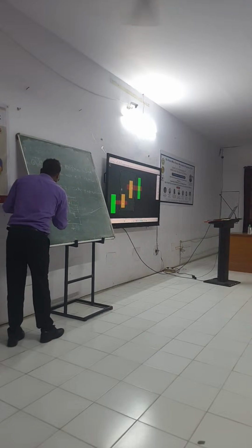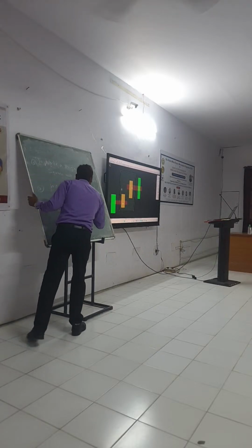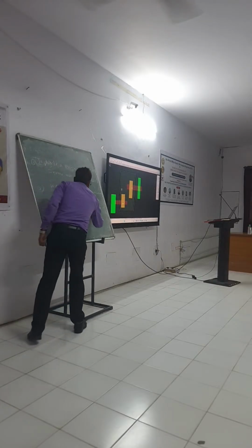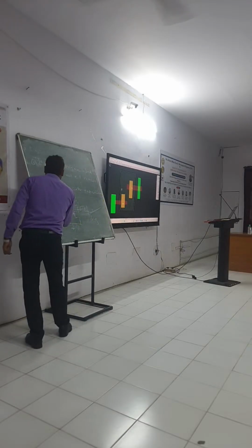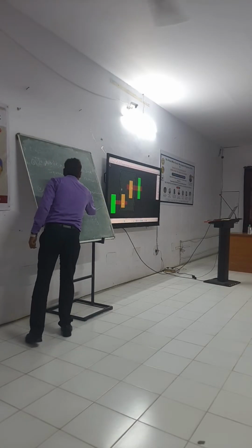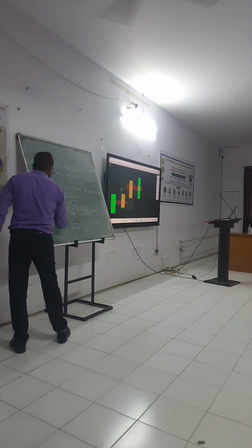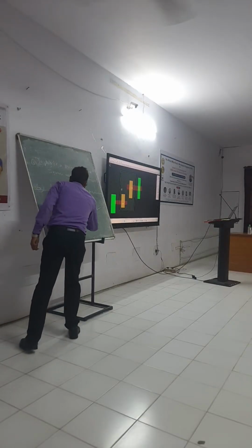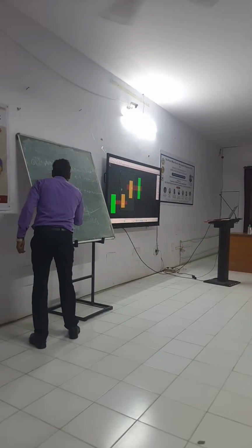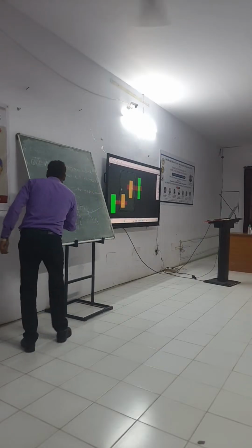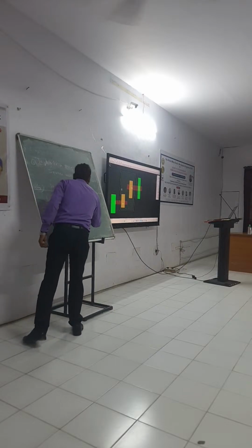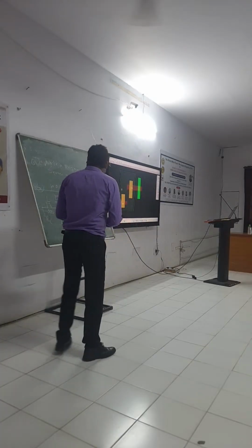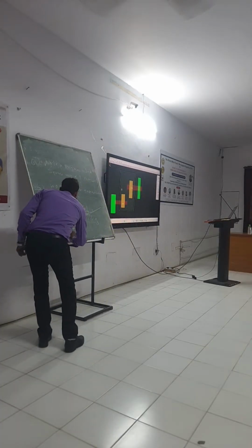So this is the access MOSFET. I already taught in first. Okay, so this is the MOSFET. This is the BL. This one is the BLB. This MOSFET can control the access which is controlled by WL. This is your BL. This is the BLB. Its name you can write Mn1, this is the Mn2, this is the Mp1, Mp2, this is the Mn3, this is the Mn4. So how many MOSFET here? 6 MOSFET. That's why its name is 6T SRAM.